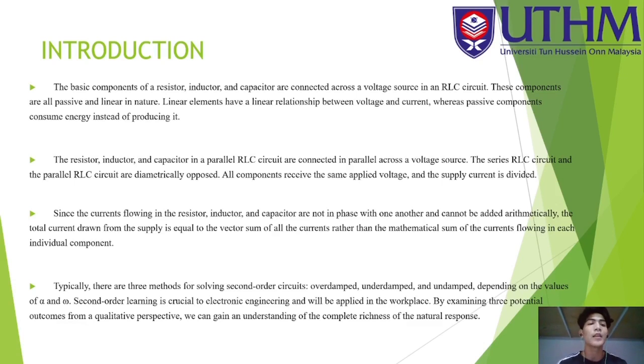Second, the resistor, inductor, and capacitor in a parallel RLC circuit are connected in parallel across a voltage source. The series RLC circuit and the parallel RLC circuit are diametrically opposed. All components receive the same applied voltage and the supply current is divided.